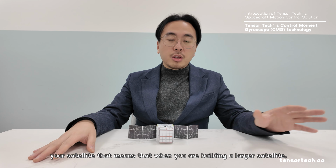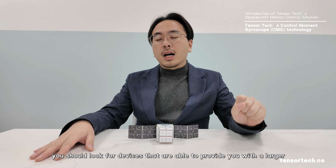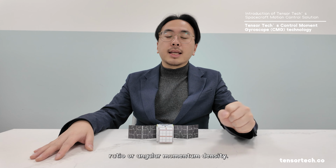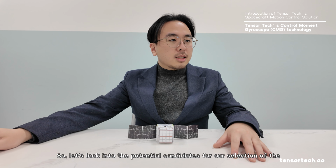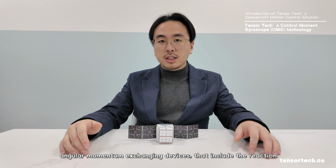That means when you are building larger satellites, you should look for devices that are able to provide a larger torque to power ratio, or an even larger angular momentum to power ratio, or angular momentum density. So let's look into the potential candidates for our selection of angular momentum exchanging devices.